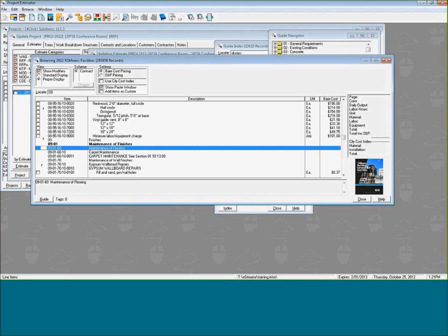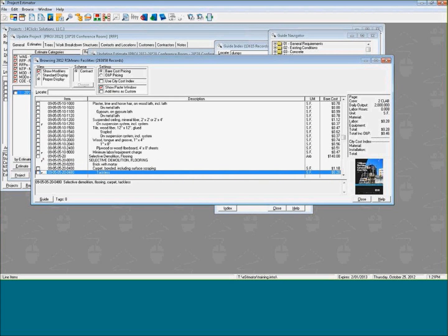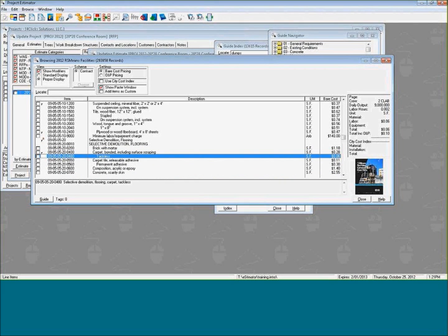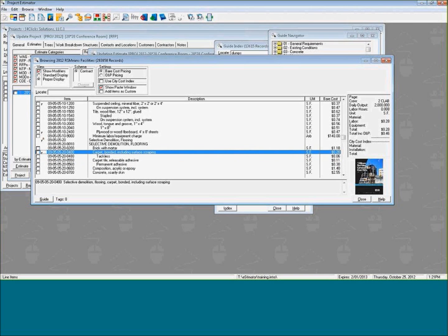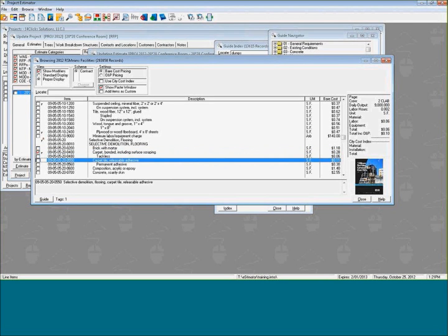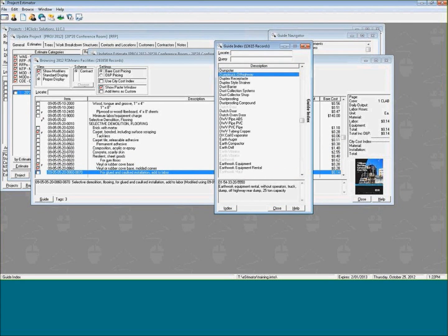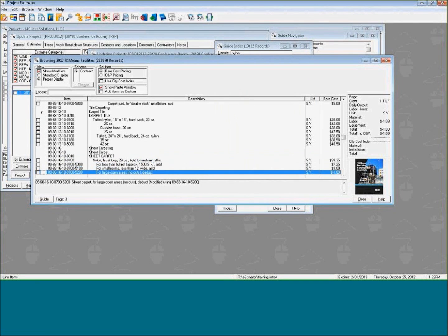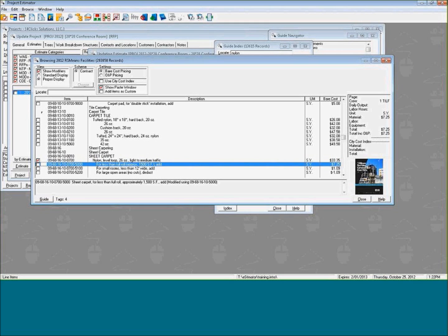So I'm going to come through my RSMeans guide and look for my demo of carpeting. What I'm going to show you now is how I can tag multiple line items within my Project Estimator and input them into my estimate while adjusting for proper dimensions and quantities at one time. So if I find my demo line item for carpet, I'm simply going to tag that line item, scroll down, find my vinyl and coat base, snap back to my index, search for some new nylon carpet, just rolling through my estimate, finding that I need for my drawing a 26-ounce carpet, so I'll tag that line item.